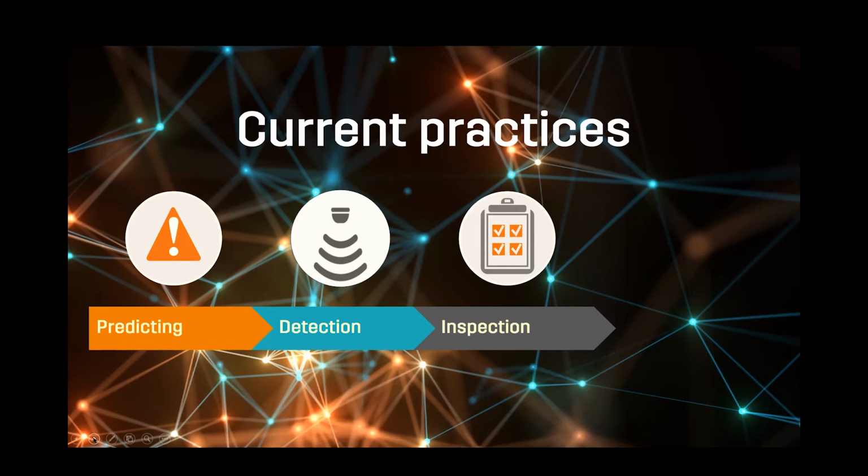We have other technologies that we've been seeing come through the market over the years. We have guided wave, which is good for long pipelines. And we are monitoring this technology to see how it progresses, because we do think it has an application in the industry, but it is classed as a screening method for corrosion. And like I say, it's best for long straight pipelines where there are no flanges.